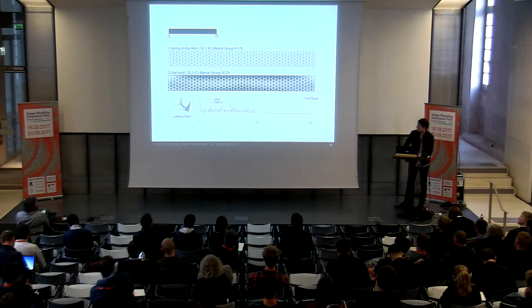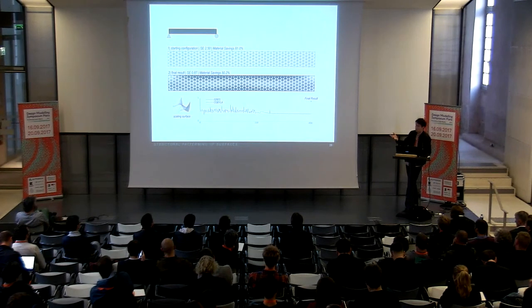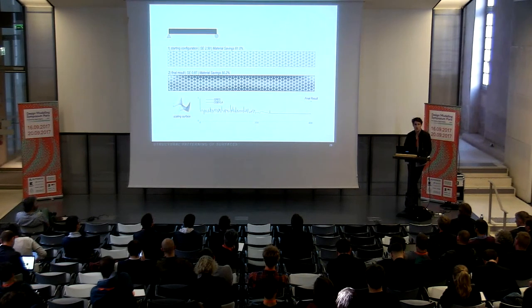Here again, we can see the optimization process with the two-pass optimizer, stochastic and deterministic, which distributed material where it is most needed for stiffness, by scaling the pattern through the control surface. And the result is a tied-arch-like distribution of material.